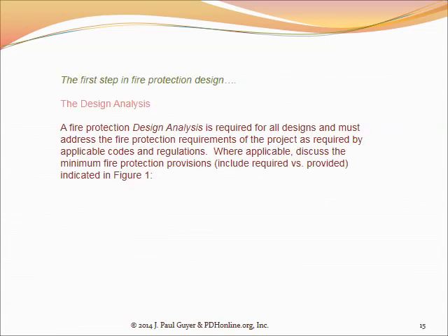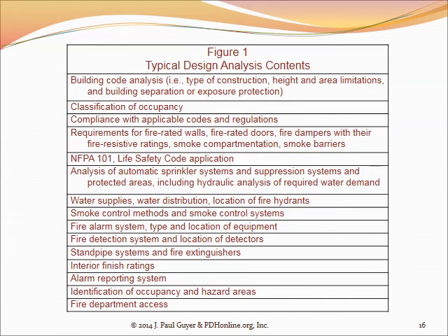First thing you should start out with when you've got a building and you're preparing the plans and specs for it is you should do what you do in all of the technical disciplines when you start out, whether it's the HVAC system, the structural system, or electrical distribution. You should start out with a design analysis. And a well put together design analysis document is a good roadmap for the plan checkers, both in the building department and in the fire department.